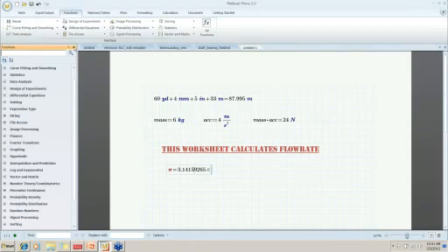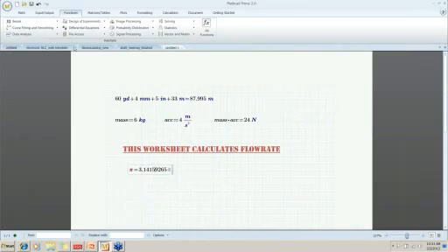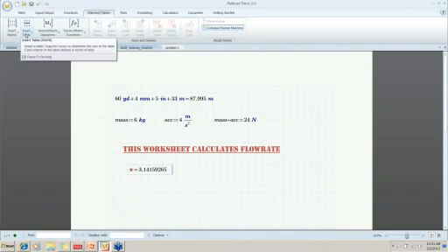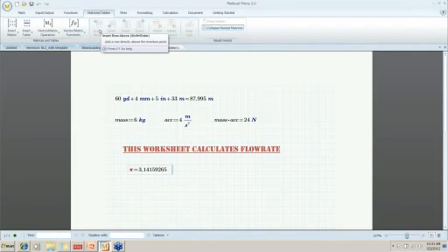So I'm going to close that, and look at matrices and tables. This is where you have all of your interaction with tables of data and arrays of data. You can insert a matrix, insert a table. A table is a spec table, so we talked about that. Here you can add rows, delete rows, very much like you can in Excel. It's much easier to do that now in Mathcad Prime. And we're going to come back and look at spec tables.